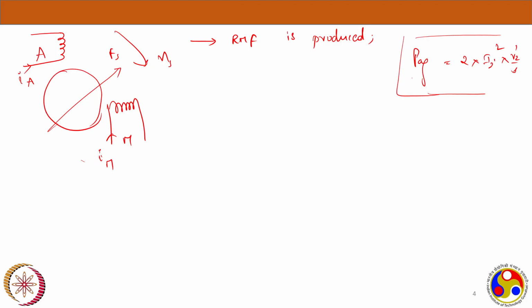But what's more prevalent in the world is a three-phase AC supply. So instead of making it two-phase and having issues with it, people will make a two-phase balanced induction machine and go for this kind of Scott connection, which you might have read in the transformer syllabus.